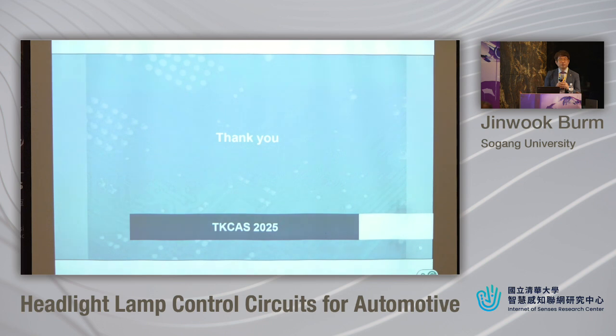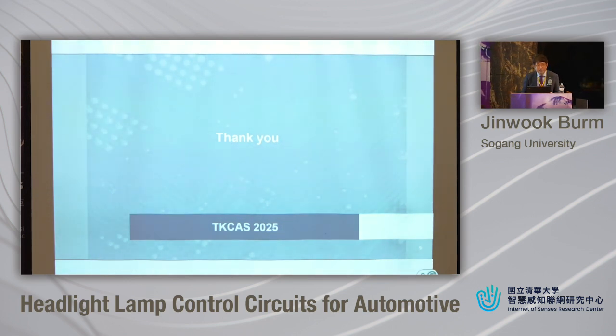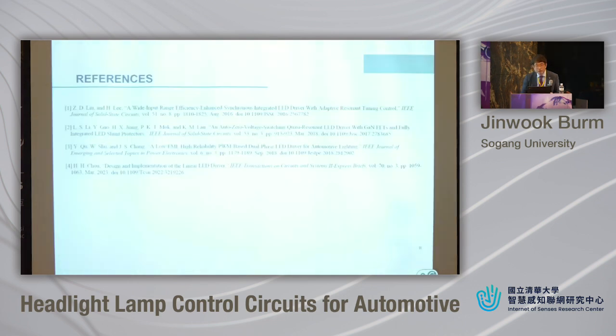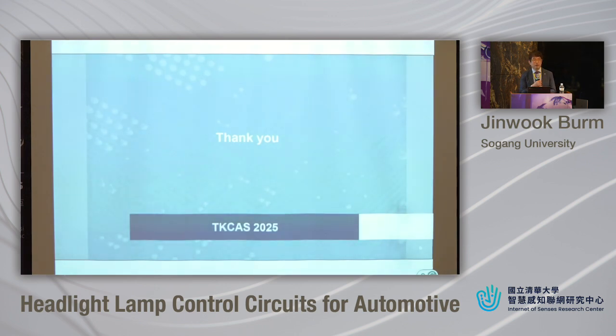Yes. Okay, I heard that you used Verilog-A to describe your current bypass and also the gate driver circuit. Is it because you also have a digital circuit design, so you want to simulate the digital and the analog circuit all together? I'm just wondering how accurately you can describe your analog circuit behavior in Verilog-A when you compare with, for example, HSPICE.